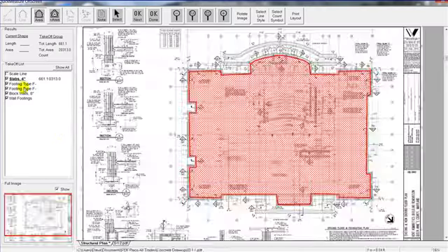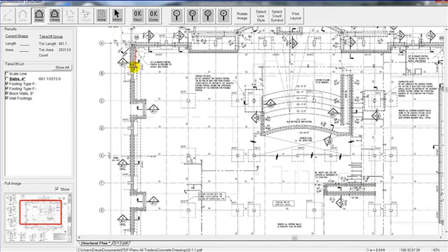So we're going to come in here. If we're going to measure linear foot, we'll just click one end of the footing, make sure we've got the footing types here. So we just click from spot to spot. There's one end of the footing, and then click the other end of the footing run. So you notice what it's going to do. It's going to total up the total linear footage of any particular footing that we've selected.